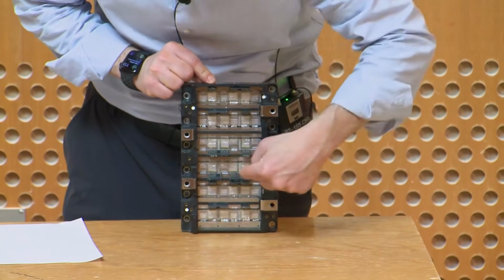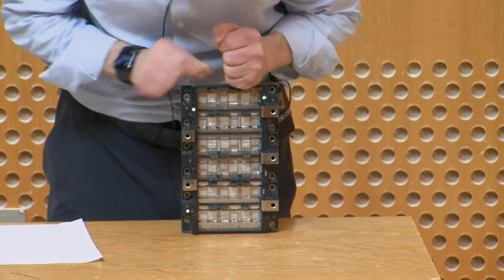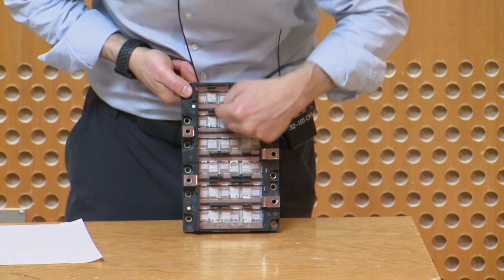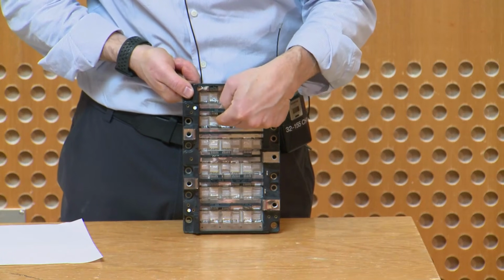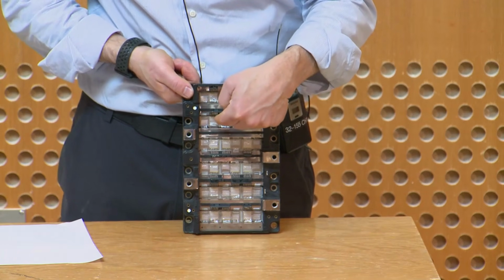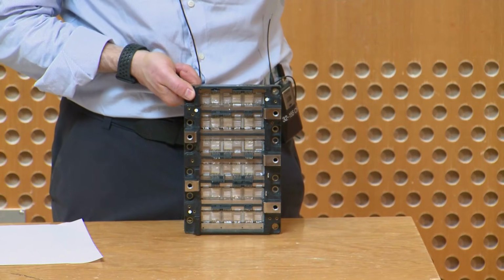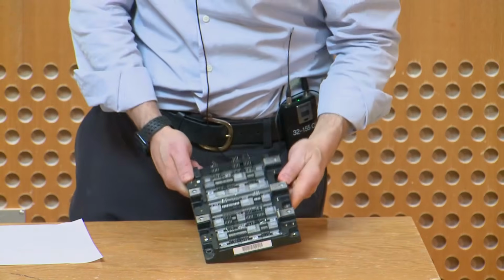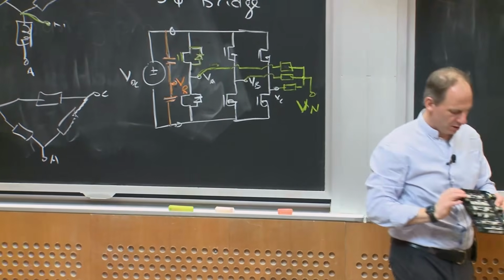Each of these, what you'll see is a pile of devices in parallel in order to provide the required power. And when you look closely at this, you're going to see that there are essentially 3 terminal devices that go back to gate drivers. Those are the IGBTs in this older model. Today they use silicon carbide FETs. And in anti-parallel with them, because the IGBT can't carry reverse current, they have actual diodes. So in their design, the actual diode is separate from the actual switch.